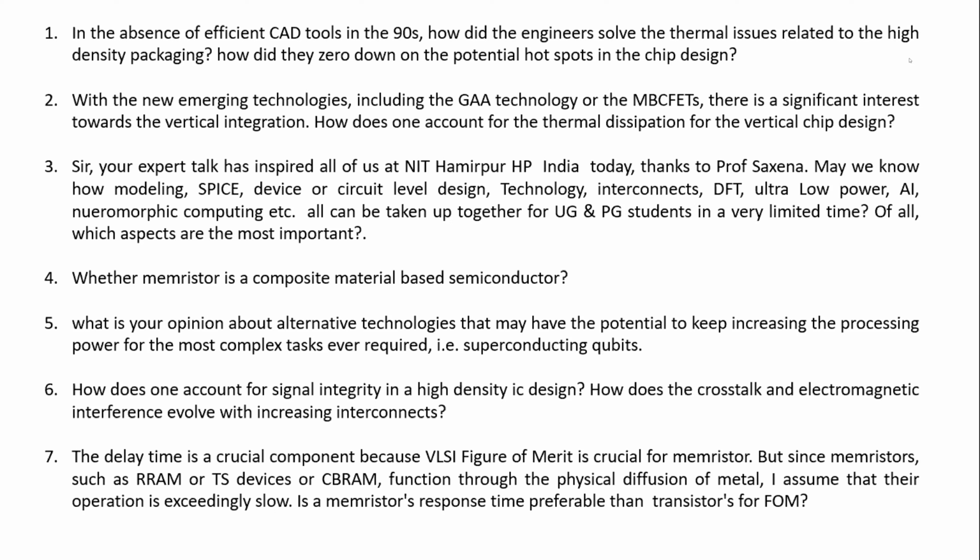But even in the 1990s, when I was at Illinois, we started introducing a simulation tool. iETSim is one of them. We included the thermal aspect. Transistors are not sitting at the same temperature on chip. On a hotspot, the mobility will be much lower compared to a not-so-hot spot, and so on.